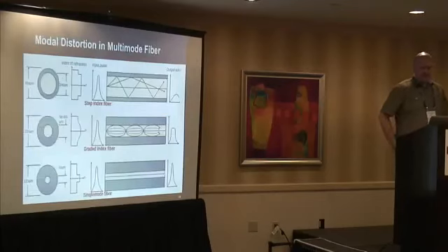So here's kind of a little diagram showing what happens inside the fiber when the core is so wide in multimode. And even inside of multimode, there's two different types of fiber. There's what's called step index and graded index. It's not really important to talk about that, but you can see that there's different types of reflections that happen inside, whereas the single mode, because it's narrow enough that it can only propagate one mode, it just goes straight. There's only one path the light can travel.